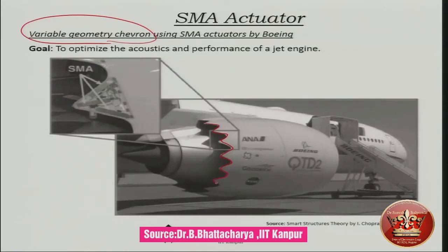The reason for this jagged shape is that initially, when it is at say detwinned or twinned martensite, but it is mostly martensite phase, at this phase it has this jagged shape, and this actually helps to keep the size of the vortices too low, so that they get attenuated fast.